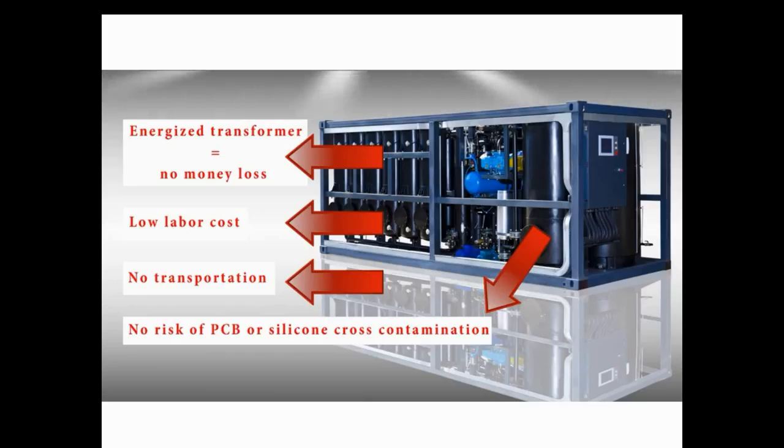Try to imagine an oil change. It's a de-energized transformer, which inconveniences clients as they're burdened with income loss. It's 10 people of operational staff as well as trucks involved, because you need to pour old oil into cans and carry it out while you are bringing new oil.